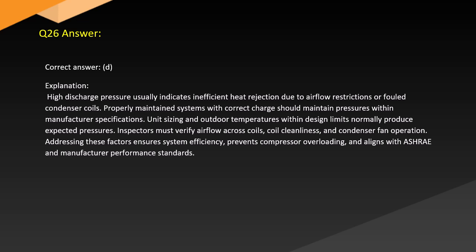Inspectors must verify airflow across coils, coil cleanliness, and condenser fan operation. These factors ensure system efficiency, prevent compressor overloading, and align with ASHRAE and manufacturer performance standards.